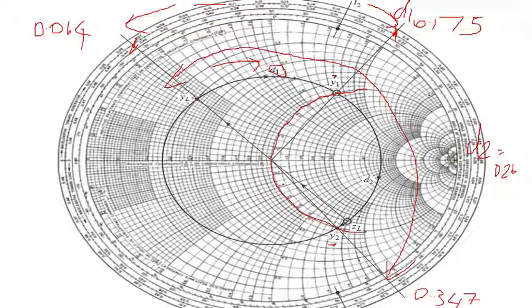Now, what will be the value of Y1? Can you tell me the value of this Y1? So this value is marked Y1 up. How much will you get for Y1? You just have to take the susceptance value up. I'm just marking it for you all, so it might be easy. When you mark this up, you will find this susceptance value is coming out to be plus j1.43. It is coming plus j1.43.